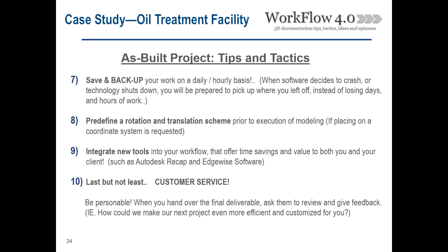Not having to move targets, especially in those really detailed and messy areas where there's a lot of pipe and supports and steel. We didn't have to worry about moving targets around, making sure our line of sight was good. We got to move the scanner right where we needed it so we could see the edges of everything that would need to be modeled, and just move through efficiently. We also could come back and do registering of each day at a time and work on that.